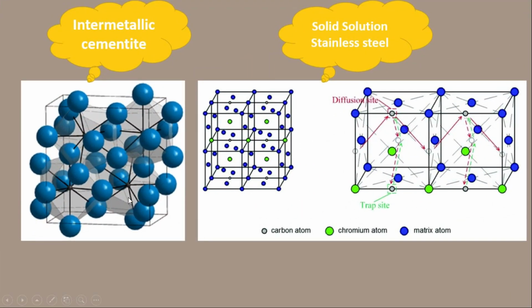While discussing solid solutioning, we discussed that when any foreign atom comes into the crystalline material, either of two cases occur. Either that foreign atom reacts with the local material and forms a new crystalline structure, that is known as the intermetallic compound. It forms a compound in a specific proportion. Another name for that one is ceramic material. Or that impure atom that comes into the crystalline structure of the host material, the solvent material, doesn't react with it. Instead it forms a mixture, and it occupies spaces within the crystal structure without disturbing the original crystalline structure. A common example for that one was steel, which is the solid solution or an alloy of iron and carbon.